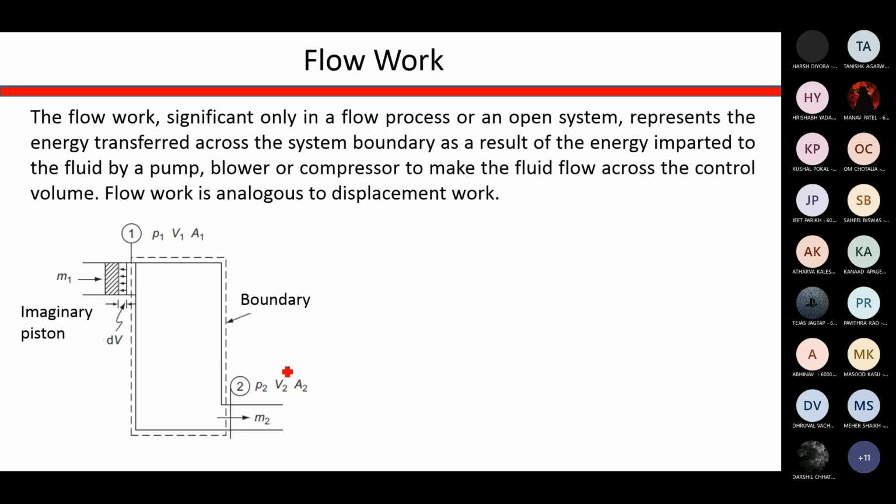Now moving further, this is an important type of work which we talk about in the steady flow energy system. So flow work. Now what do we mean by flow work? This may look pretty analogous to PdV work, but it is different from PdV work. So the flow work is significant only in a flow process or an open system.